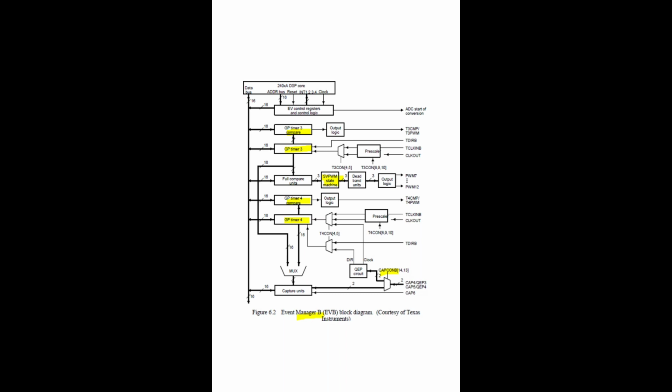This special PWM generation, space vector PWM, will be used to control the harmonics output of any converter. This kind of PWM is specially used to control the ripple. If the ripple or harmonics is reduced, obviously the efficiency can be improved. But in this chapter we are not going to use space vector PWM.